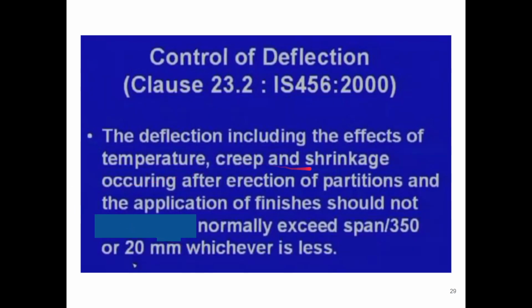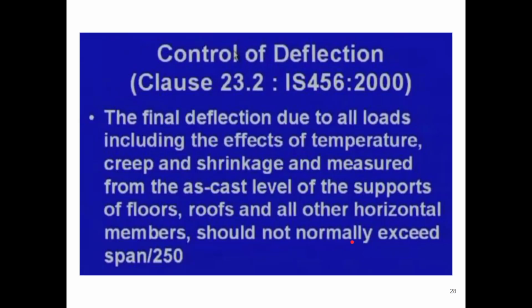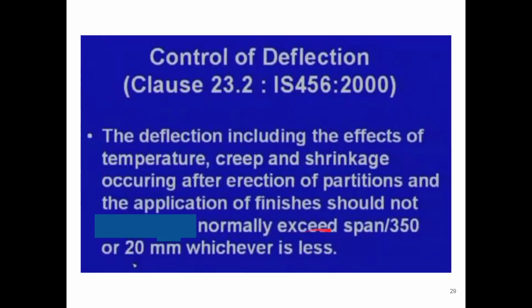And after that, if we have partitions inside the building and we have applied finishes, that will also create some load, right? So after including all those loads, the value should not normally exceed span by 350, or 20 mm, whichever is less.